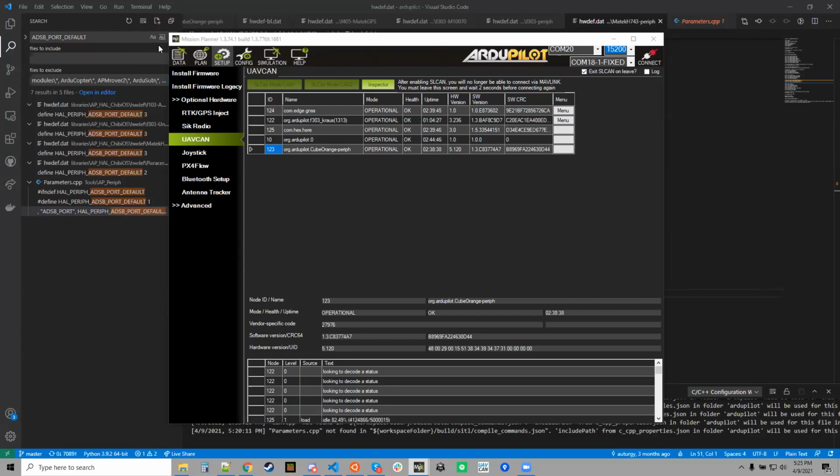Well, right now it requires ChibiOS for all of our parsing and stuff, so that's limited to our STM32s right now. Yeah. Well, there is a ChibiOS port for Teensy. There's ChibiOS for it, but all of our scripts are basically hard coded to only support STM32s. So someone has to do all the work of the driver, and that's based on the ChibiOS hardware-defined system.